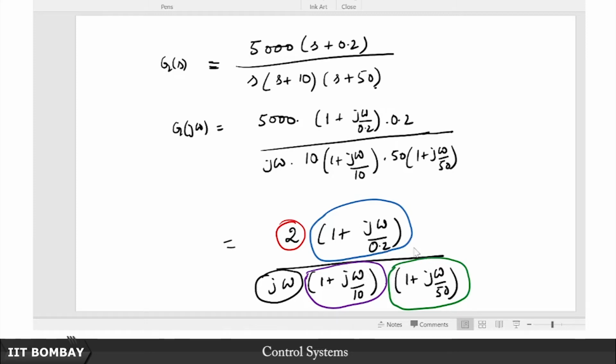So these first order and second order factors having real or complex conjugate poles and zeros would all contribute 0 dB at very low frequency asymptotes. The only contributing factors would be the constant block and the integrator and or differentiator, if there were any. In this case there are no differentiators, there is only one integrator, it is a type 1 system.